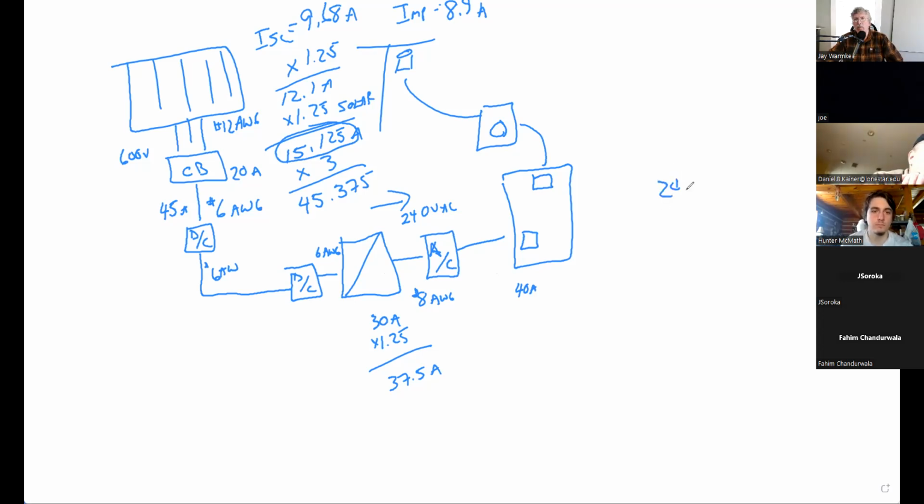If it's 240 volts, 30 amps, then we're going to be, is that right? 8? 7? Oh, wait, did I do it wrong? Nope, 7.2. 7.2? Yep. All right. So this would be a 7.2 kW inverter.